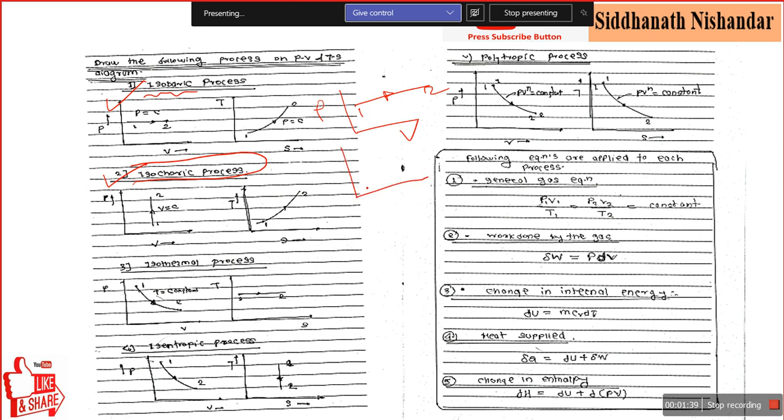On TS, when we add the heat, the temperature as well as entropy is going to increase from 1 to 2 on a TS diagram. Also always remember, the area under the PV diagram indicates work done by the system. The area under the TS diagram indicates what amount of heat is supplied or rejected by the system. These two areas we use the values on a graph.